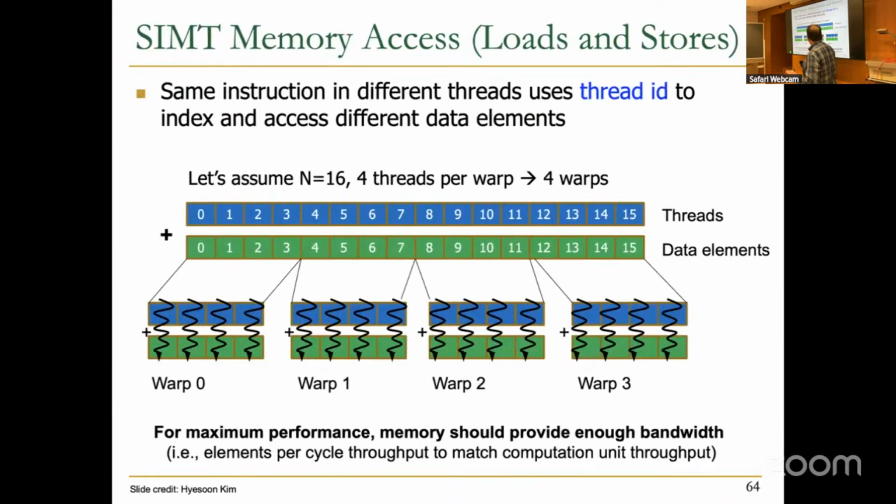And that's not only the off-chip memory or the GPU memory; the register file should also have high bandwidth, because the register file in GPUs is actually quite banked. There are several register banks, and there are multiple operand collectors that fetch register values, prepare them, and then feed them to the pipeline. So we need high bandwidth everywhere in the GPU, because if you don't have that bandwidth, fine-grained multithreading is not going to work well for you.